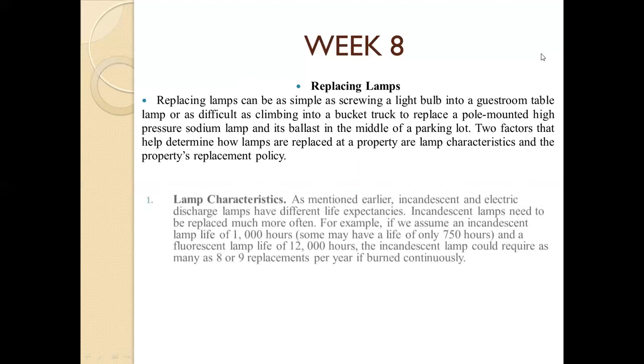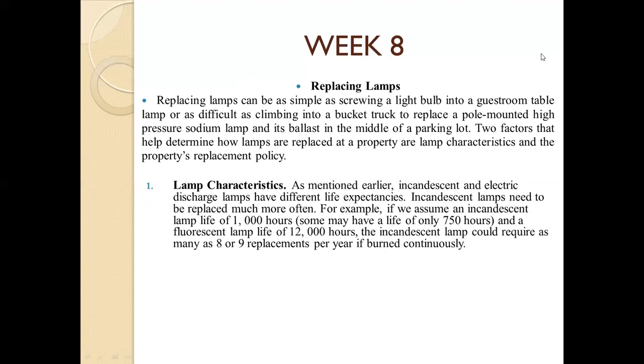As mentioned earlier, incandescent and electric discharge lamps have different life expectancies. If you have installed incandescent lamps, you should anticipate or create a replacement program for your housekeeping employees, since incandescent lamps need to be replaced much more often.